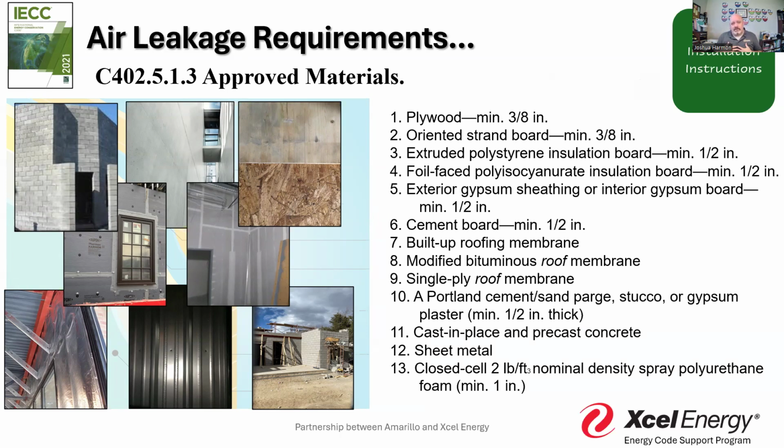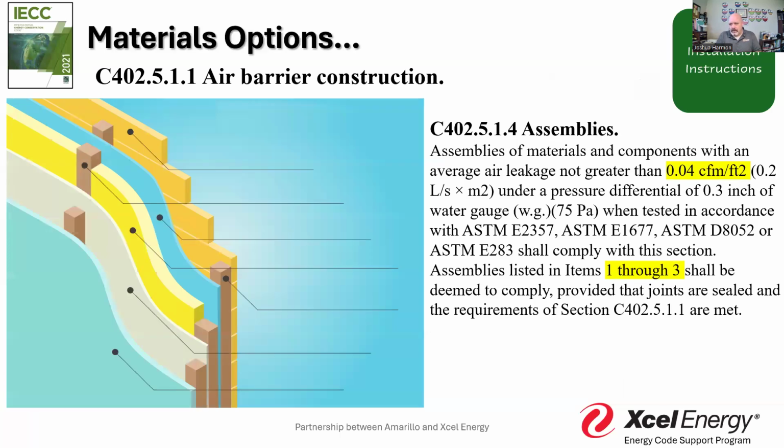And I would always, as the building official, say, hey, okay, you've got OSB in there, you've got multiple components that could perform as an air barrier. Which one are we talking about, right? When we come back to test this, where's the barrier? Where's the final line in the sand on how this is going to be tested, right?